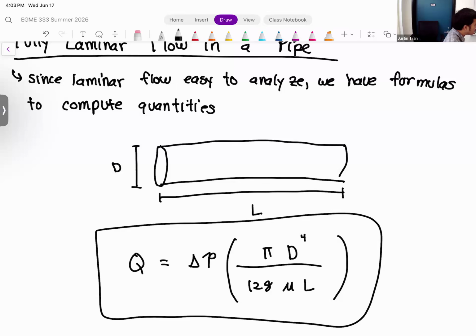But generally speaking, as you increase the flow rate in your pipe, the pressure drop also increases. That's consistent with what we just talked about, where viscous effects get stronger the faster the flow is. So the more volumetric flow rate there is, the stronger the viscous effects are going to get, so you need a higher pressure drop in order to maintain it.